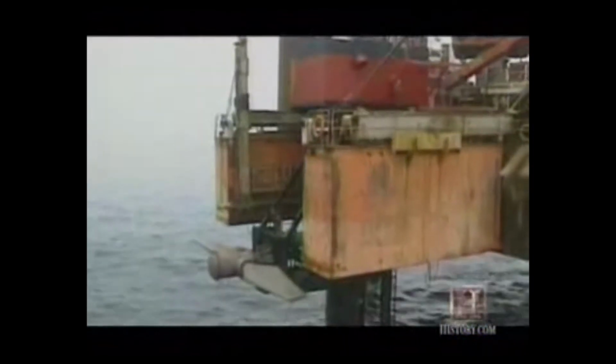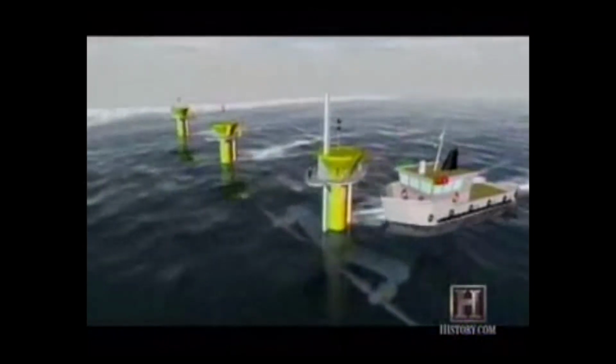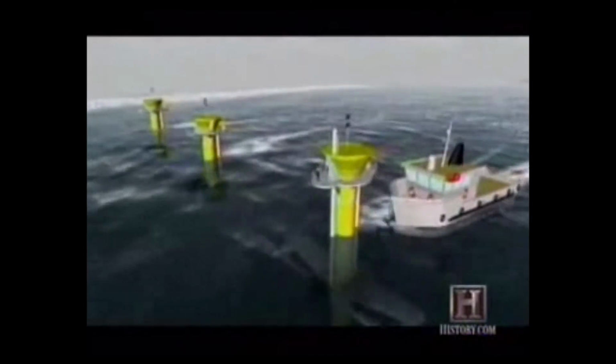Much of the work is taking place in the British Isles, where companies such as Marine Current Turbines are thinking big, sinking massive pilings into the ocean floor and letting the turbines do their work. And the amount of energy you get out of a turbine is proportional directly to the density of the fluid that flows back and forth. And so a water turbine has several hundred times the power of an air turbine.